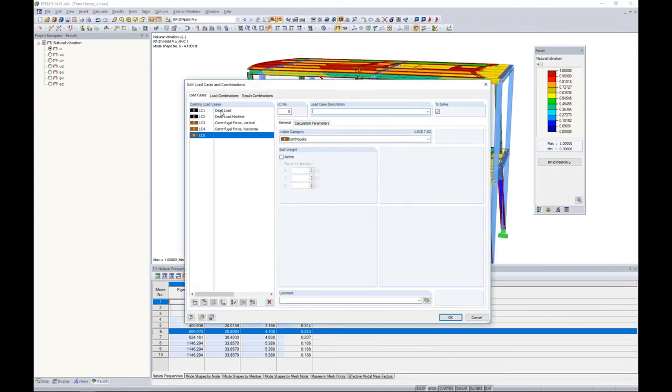Now, remember, load cases are something that I apply my dead loads to, or I applied my centrifugal forces to. Well, for this 5th load case, I'm going to call this one tension only deactivation. And I'm not going to account for self-weight. I'm not going to apply any loads whatsoever to this load case.